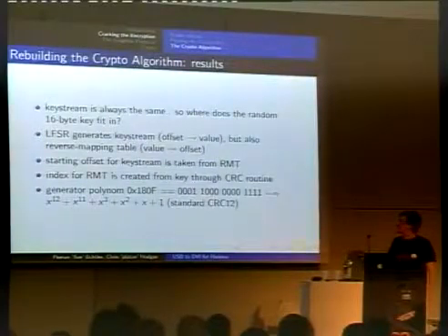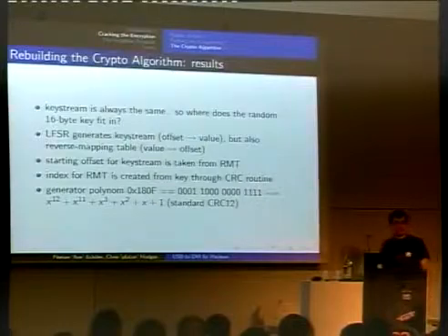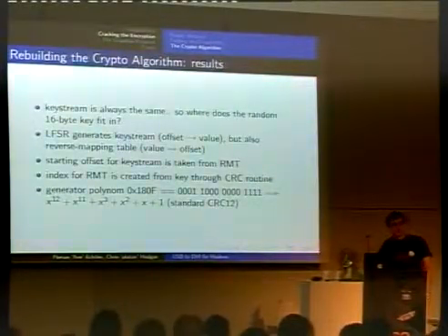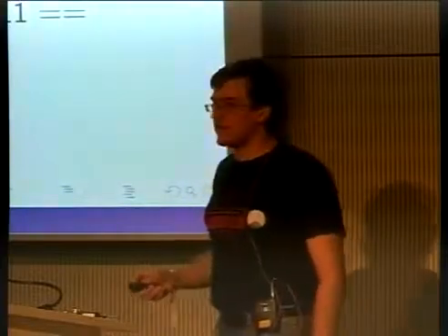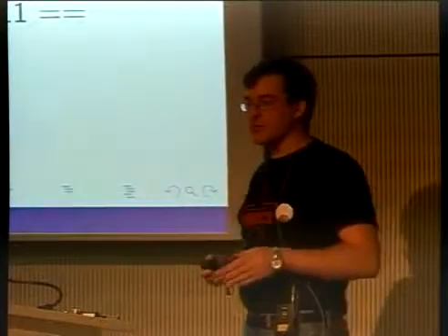The CRC of this key is just fed into the LFSR on the device, which then starts generating the same key stream as in the driver. So this is in fact a standard CRC12, and it looks like the device doesn't even generate the entire key stream in memory, but just always pulls a single value from the shift register and then advances it by 1.